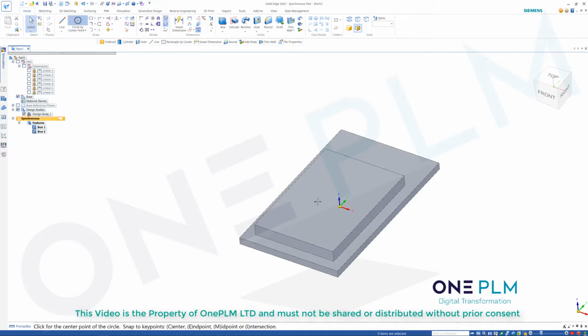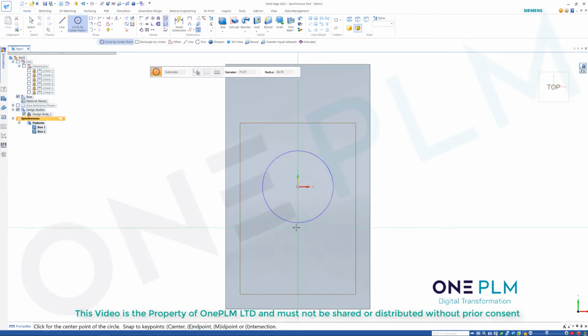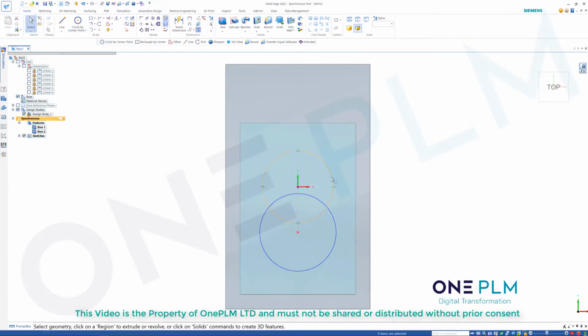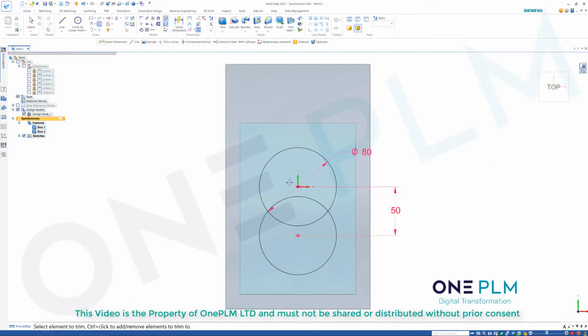Next I'm going to do a drawing. No idea what this product is, but we're going to do a circle on there, and we're going to do another circle. I'm going to bring that down to there. Now I'm going to do an equal command between those two. I'm using the new 2022 equal command. I'm going to use a smart distance and choose the centers of those two. So you press the C key, hover over the arc and press the C key, and that will allow us to pick those centers. Let's do my smart dimension, and we'll keep that pretty similar to what it is. Let's do a smart trim, and we'll get rid of those. And we've got our profile looking pretty good.